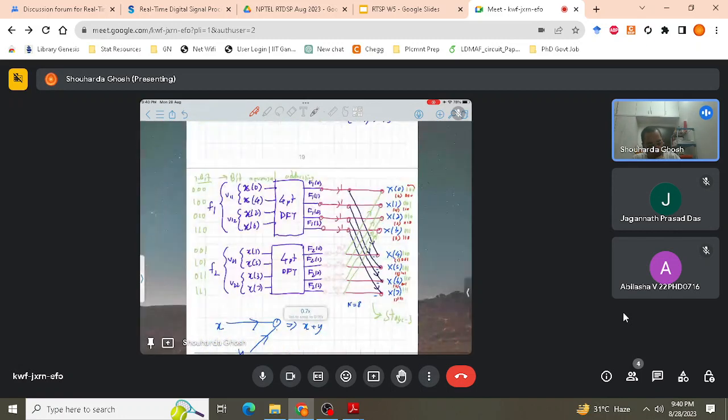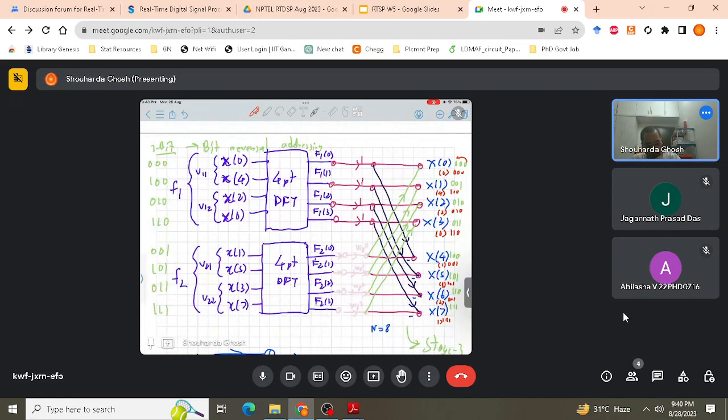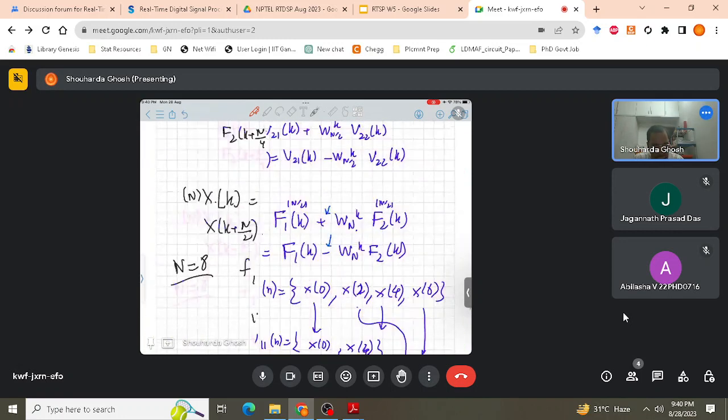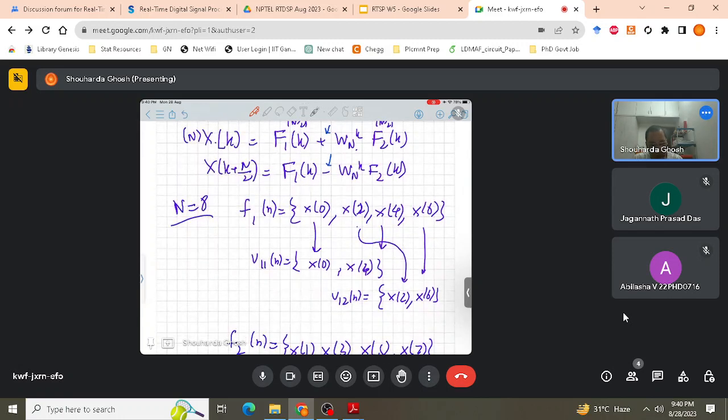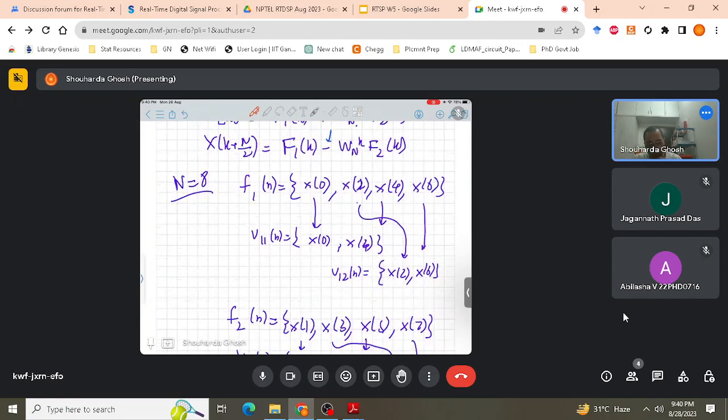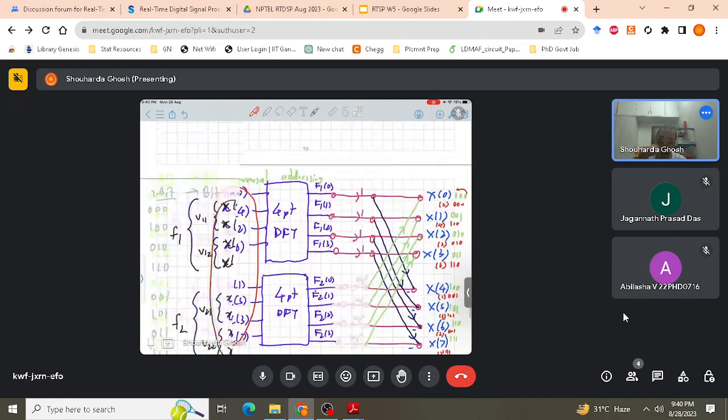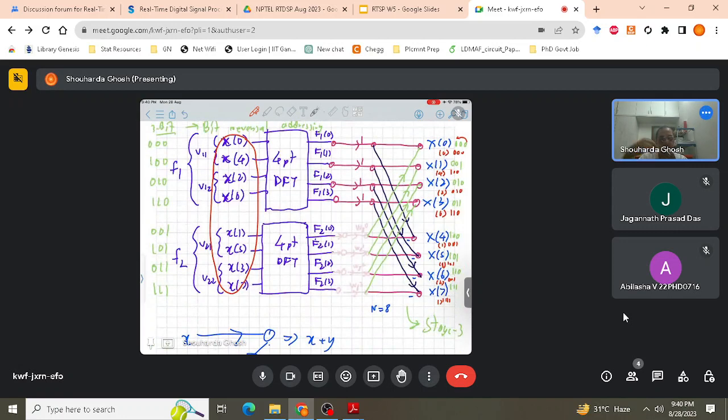So in the normal order, when you do bit reversal, this is the way in which you access your elements, these signals, and we have decimated the signal in the time domain. We have taken the signal x of n and taken even samples, then further taken their multiples of 4 and then shifted by 2. That's why it's called decimation in time.